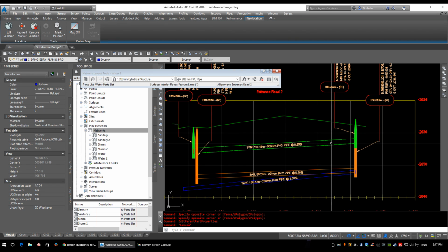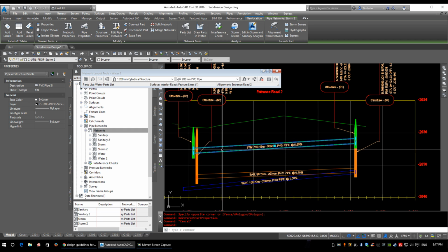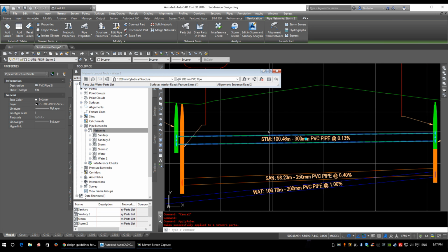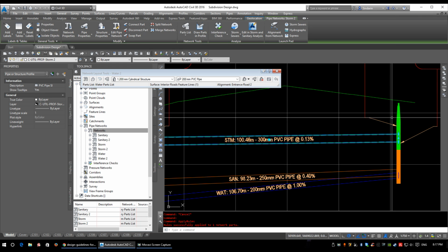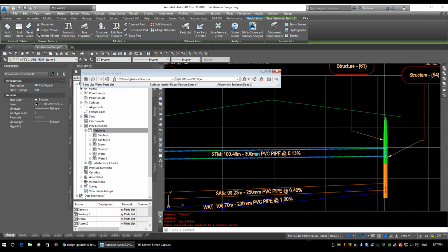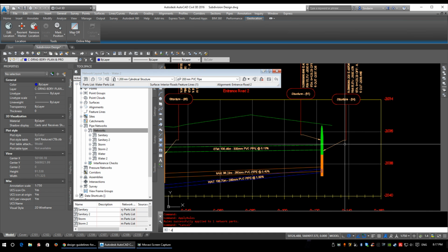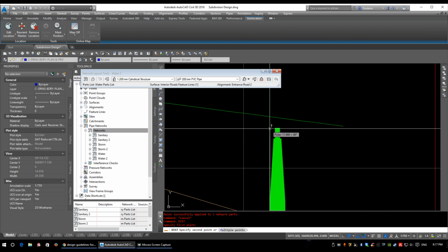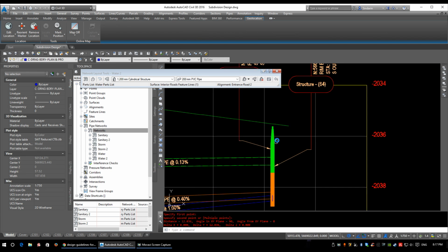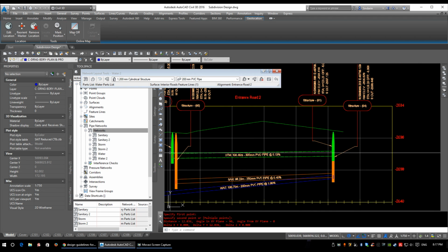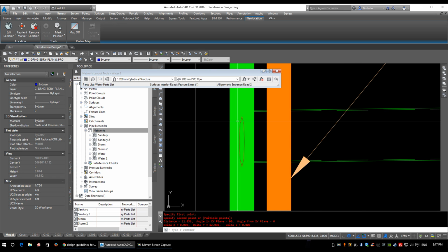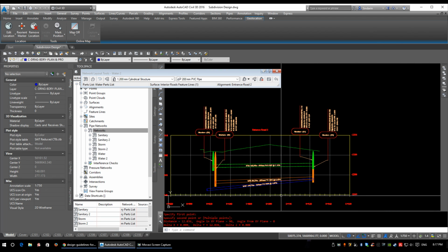Now we set up these rules. We put our structures in. Did they really work? Again, you can select one of your pipes, right click and apply rule, and we'll see if this makes a change. So it lowered the pipe slope. It didn't keep the proper depth. So again, storm pipes, we put 1.2 meters underground. Let's just quickly check if it did the proper depth. So distance from there to the ground, or the manhole top, yields 1.2. So that actually did do the proper depth. Before, it held the slope or something or other. If we look at our structure style, this is the red circle, that's the incoming pipe.